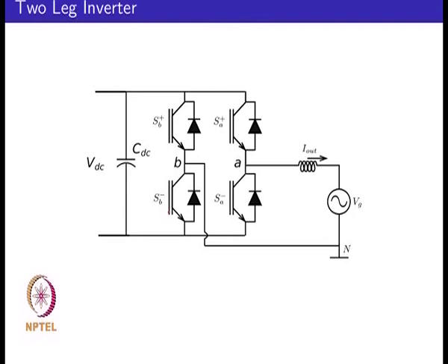So, from a thermal loading perspective, the temperature rise on one leg would be more compared to the other leg. So, if you are using a H-bridge module, you may not be fully utilizing your semiconductors. So, you will have to look at all the factors in mind to look at what are the advantages and disadvantages of one particular topology or one particular method of operating your switches in a power converter.